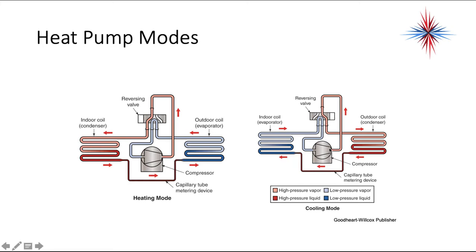In cooling mode, the reversing valve is slid over, and my discharge from the compressor goes through the reversing valve into the outdoor coil.